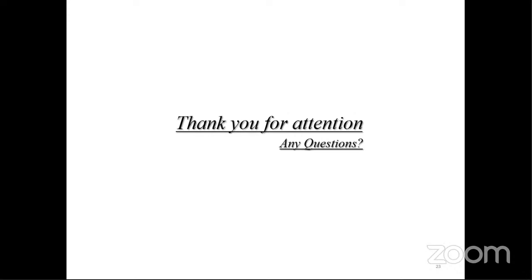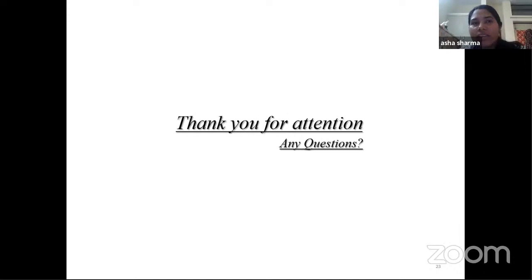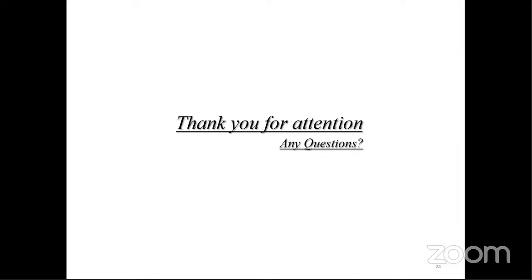Ma'am, in the withstand test, both in AC and DC, you are keeping the testing time at 1 minute. Is it standard or can I change the time period to above 1 minute? I have told this also: this presentation was a very general presentation. I have not concentrated on a particular apparatus. So according to the requirements of the manufacturer and the customer, we can increase this time. But as a general IEEE standard, it is 1 minute.